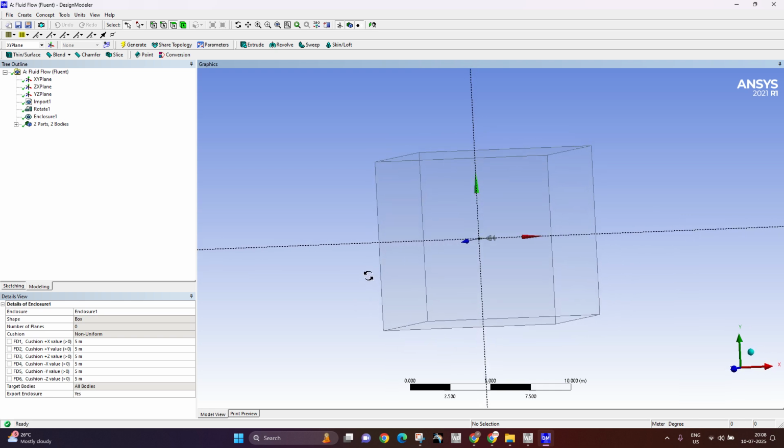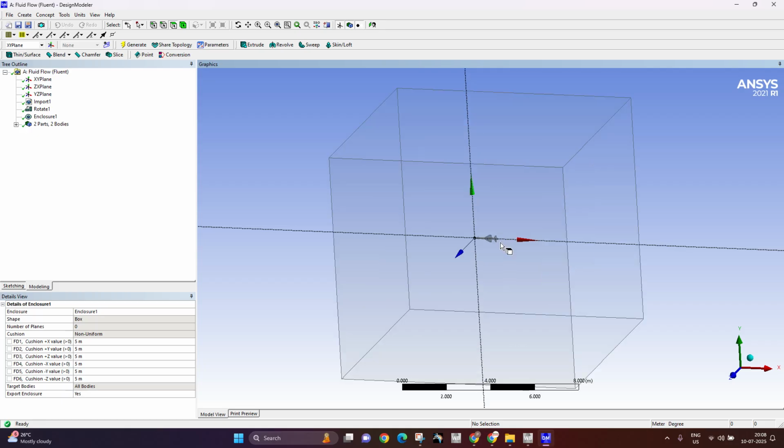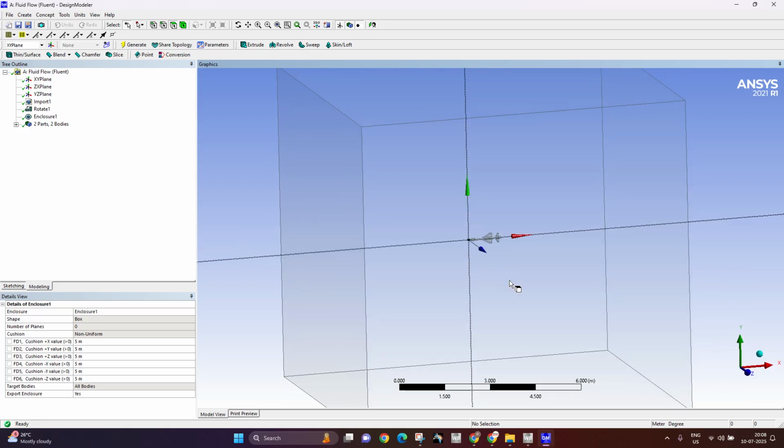The reason why I apply a bigger fluid domain is because you will be able to track the shock waves, the stagnation point, any sort of vortices inclination or environmental reaction. These things can be spotted very quickly and better. So that's why I want a bigger environment.